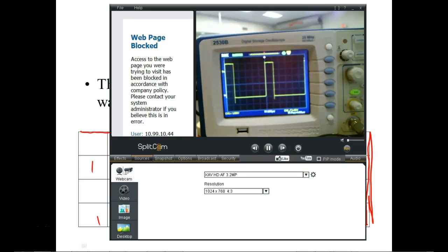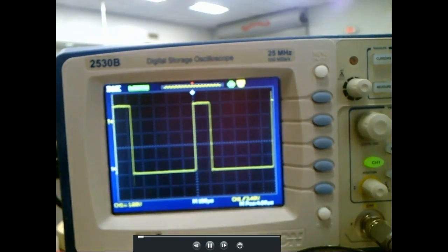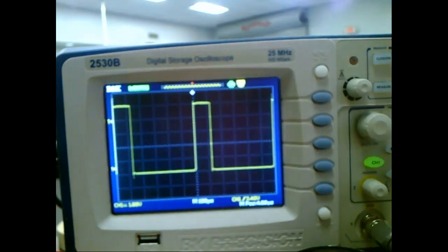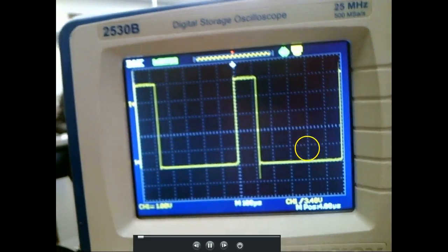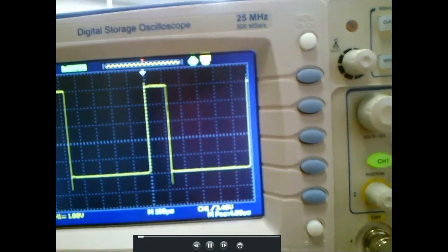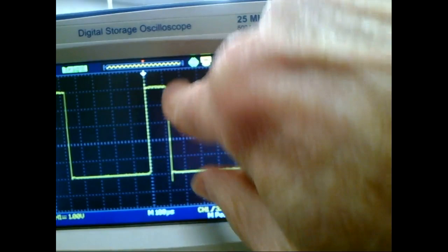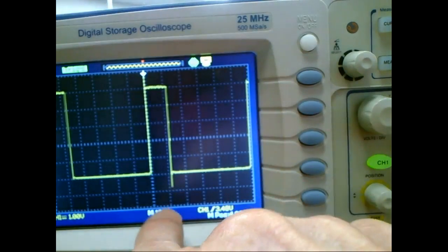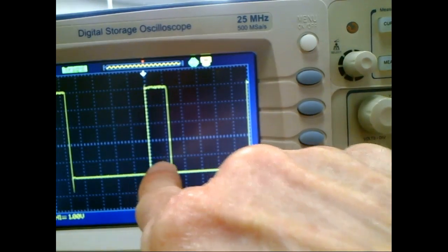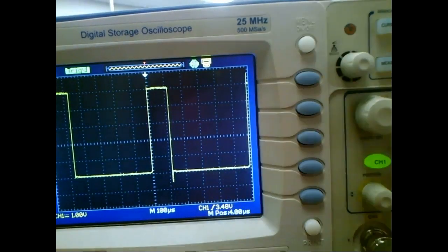The first thing I have to do is identify a cycle. So this is my oscilloscope. A cycle is one repetition. I can't see this leading edge over here real well, but I can definitely see this one over here. So we've got it over 1 minor division. So my time is 1, 2, 3, 4, 5, 6.